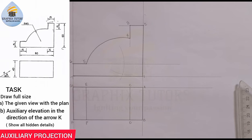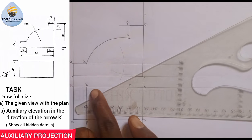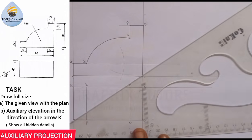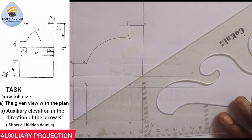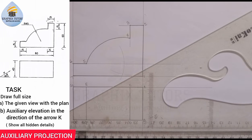After you've done that, since we are told it is being projected, we look at it from this side at an angle of 30 degrees to the horizontal. How do you know the horizontal? When you see this horizontal line here, and the angle is 30, this will be the horizontal line and this side is 30 degrees. So your set square, when it's standing this way, this side is 30 degrees. So I will place my instrument on my T square. It is effective when you use it with your T square.